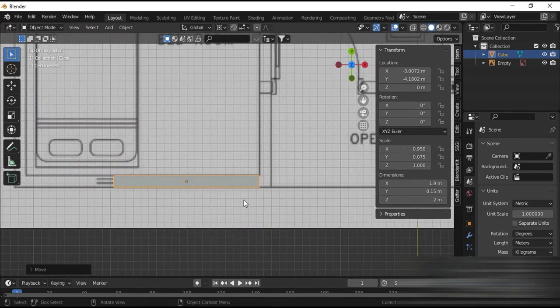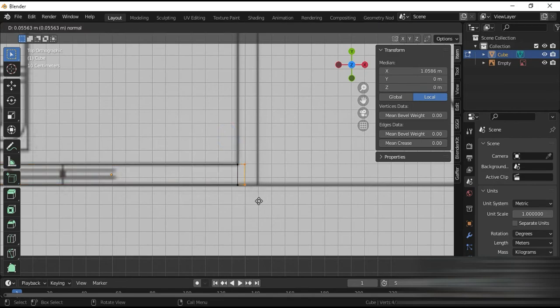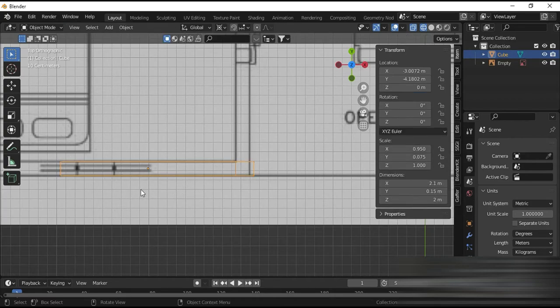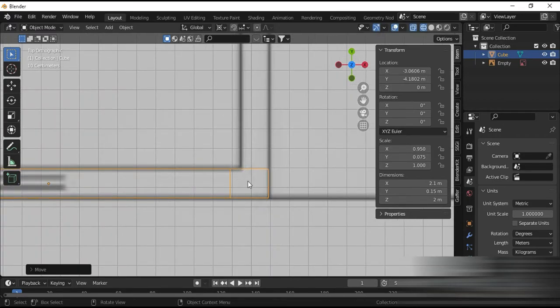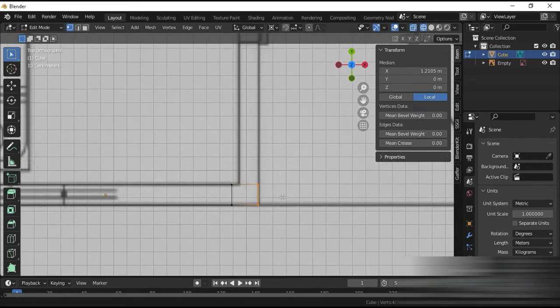Okay, now edit mode, and Shift and Z, and we selected this, so E and 0.2. All right, so 0.2 is 9 inches. Okay, I'm trying to make a column with this. This is sort of a column that we have. So you know what, let's G and X. Yes, but this is more, but it's fine. It's fine. It's because of the image.